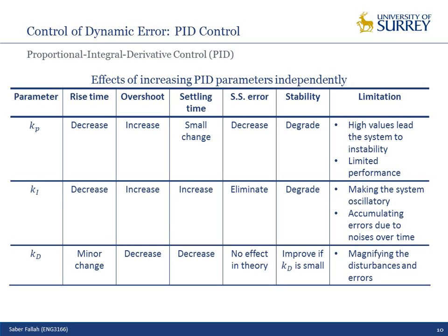Does the steady state error decrease with Kp? Will steady state error get lower as you get a higher gain? No. Look, as I said, it's not a general case. If you look at the example I ran for you in MATLAB code, if I just use the proportional control, the steady state error will be increased. Yeah, but because it wasn't well tuned. If you tune it well, you can decrease the steady state error using the proportional control.